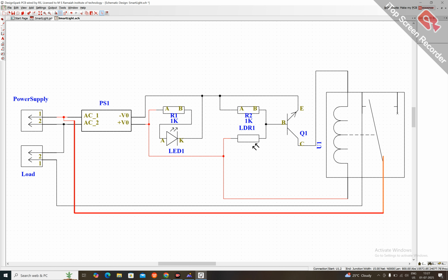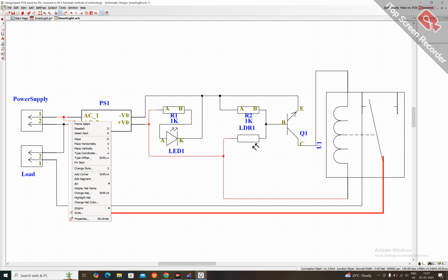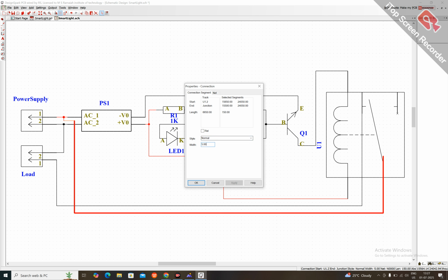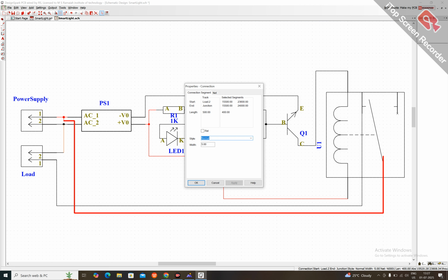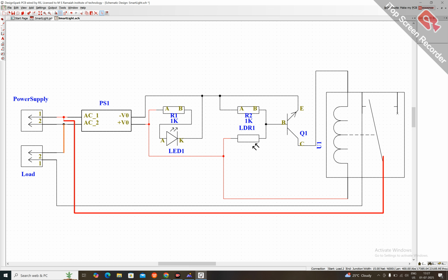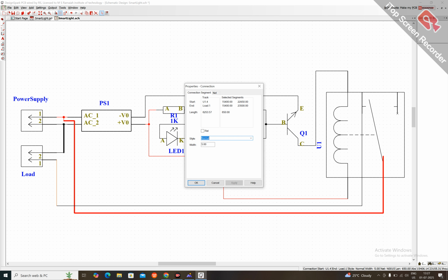Yeah, I can observe here. So this is the power. Power is becoming 15. So for the high power connection, I'm making it 15. Low power will stay as it is. Like this, you can even change the thickness of the virtual connection. It is not actually a track, it is just a connection thickness. Understood? It just indicates that those are all high power.